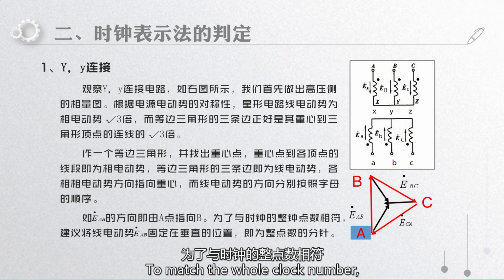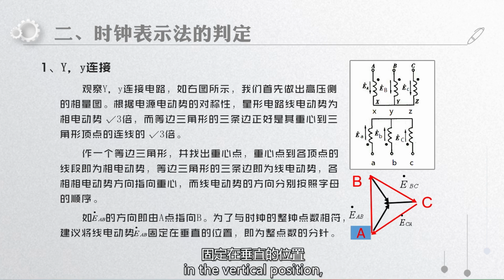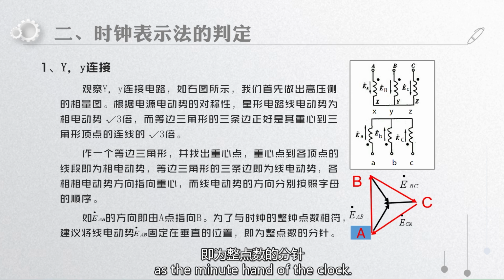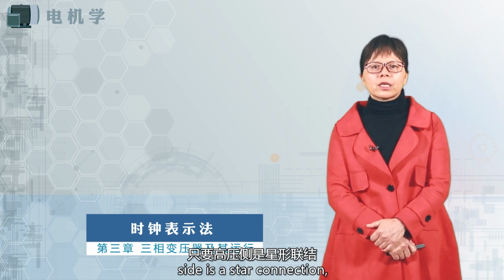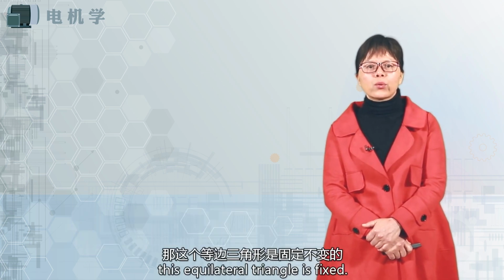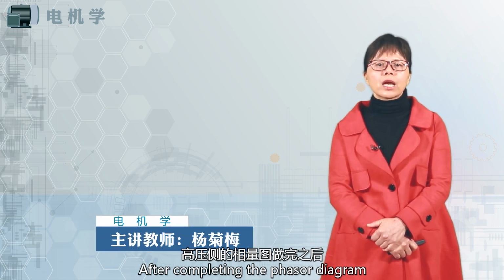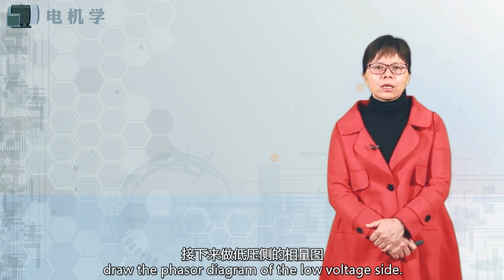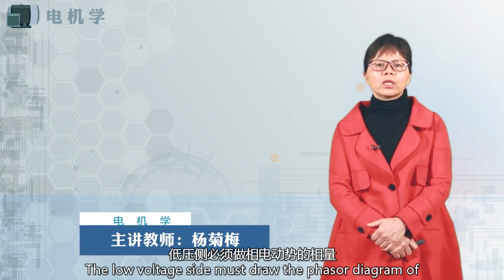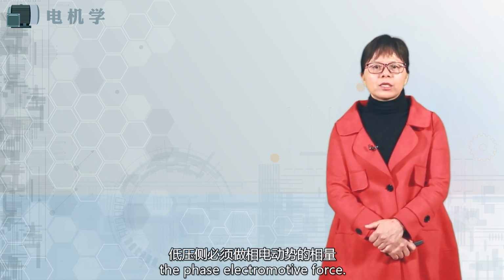To match the whole clock number, it is recommended to fix the line electromotive force EAB in the vertical position as the minute hand of the clock. Remember, as long as the high voltage side is a star connection, this equilateral triangle is fixed. After completing the phasor diagram of the high voltage side, draw the phasor diagram of the low voltage side. The low voltage side must draw the phasor diagram of the phase electromotive force.